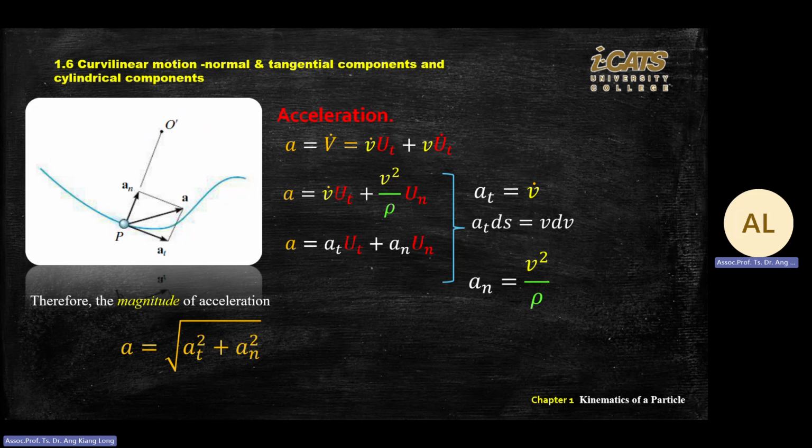Okay, tangent, normal direction. So normal always pointing in according to the curve. So use your palm. The face of your palm is actually the normal direction. And then the tangent direction is always 90 degrees to it, the same direction as your speed, as your velocity. Remember that. So all the calculation, we are focusing on tangent direction.